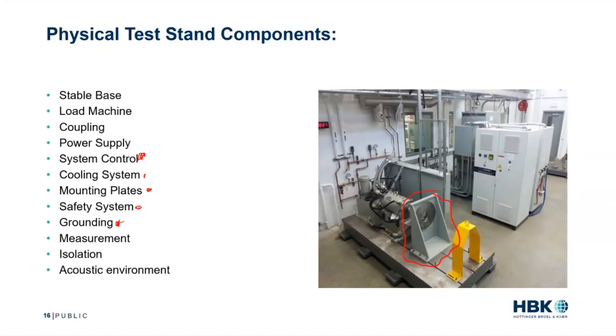Or going through and measuring your grounding tree and making sure you don't have loops. This is going to help your data for all those types of tests we mentioned, but especially when you start throwing in lots of accelerometers, lots of microphones, lots of ways for electrical data to get somewhere. You really just want to make sure everything is as clean as possible and that you're going to have that high integrity data. So check your grounding loops.